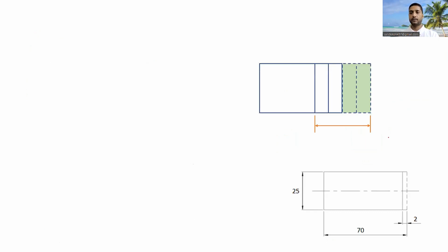So this diagram shows that till now we have removed this much material. The total length which we will remove is 2 mm, and 1 mm we have already removed. And the tool is right now at X26 and Z5. So let me just show you the X26 line. We know the diameter of this workpiece is 25 mm.